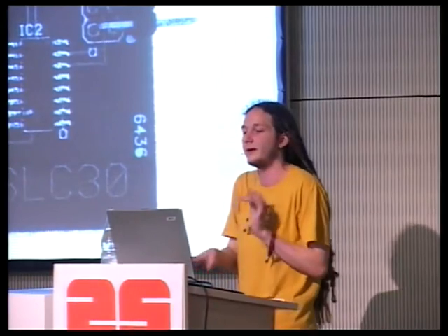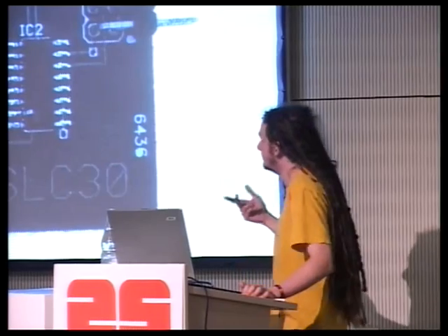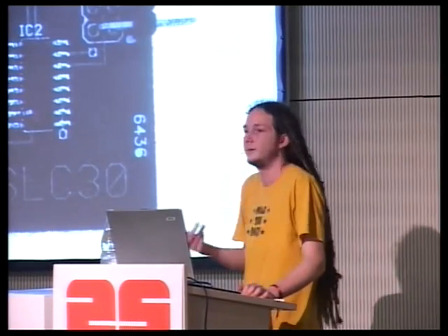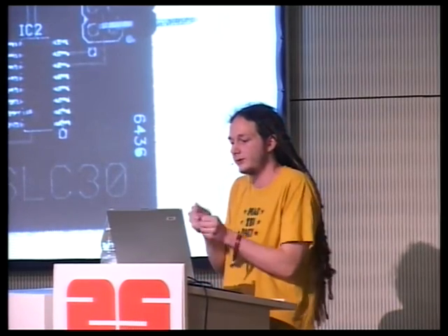And at this point, all of the I/O lines are switched to high impedance so that no power can be sucked out of them. And then the voltage line drops to a lower voltage that's controlled by an I/O pin. By use of this, you can glitch past a disabled BSL. With better firmware, you should be able to glitch past the password comparison itself. If you glitch through it such that it never actually compares a byte, then it can never disable your access.